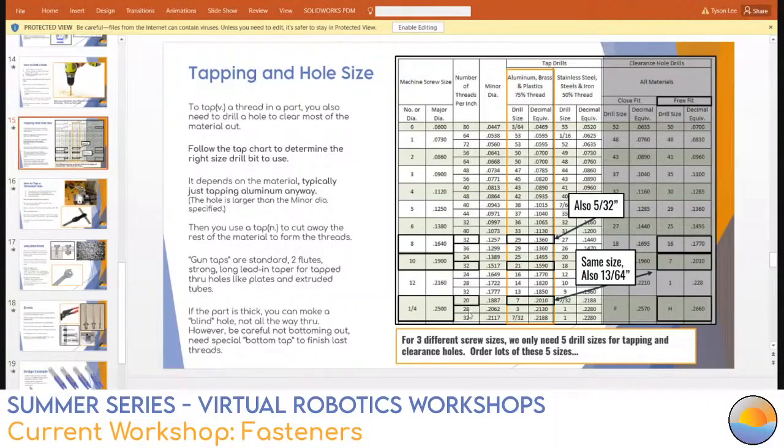That sounds great. Jacob from Code Orange asked, what drill and tap chart do you use? And we can tell he's from Code Orange by his wonderful profile picture of one of their last robots. There's a tap chart in every shop, and you're going to see a tap chart just like this in almost every shop. But the point is that you can use any tap chart. These descriptions might be different, but if you standardize these screws, you only have to use 3 different sizes on the tap size, especially if you're using aluminum. They're all going to be the same because they're all based off of a mathematical standard and the machine design handbook. There are proofs for all these, and it's an upper level class that I'll admit I dropped because I found it so boring. Right here you have all the information already done for you.